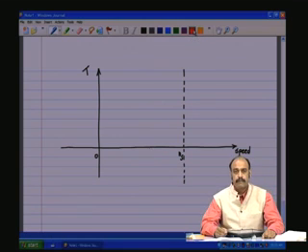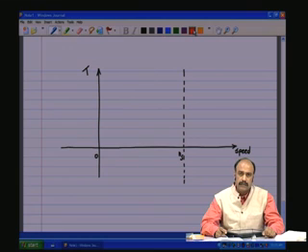Now at standstill there is the rotating magnetic field which is rotating at synchronous speed. Then there is a slip of 1, a large difference in the relative speeds between the rotor conductors and the rotating magnetic field.